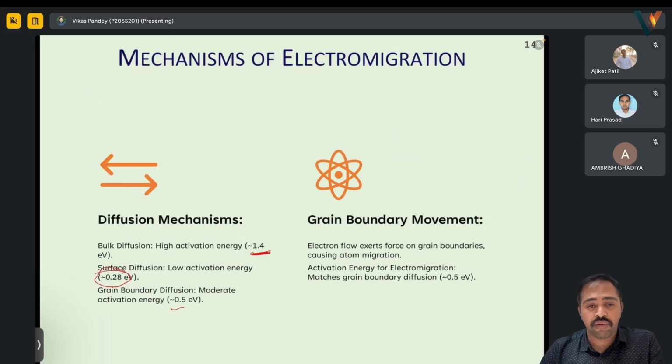It is tackled by alloying, or you can say doping, these metals. Like copper is mixed in aluminum. Adding 4% copper reduces electromigration by slowing down self-diffusion. Self-diffusion is lessened. As well, it has been observed that copper-doped aluminum takes longer to fail. So that's better. We get less electromigration there.